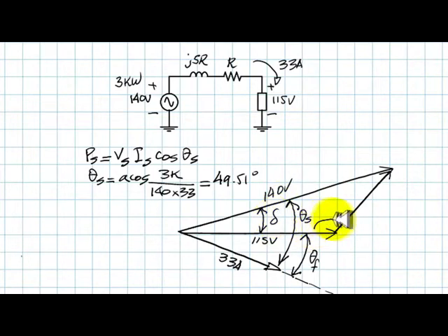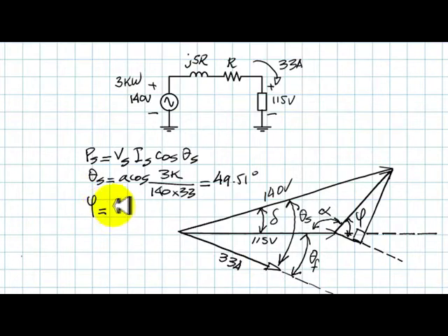Can we find perhaps this angle? What angle is that? That is alpha, right. How? Well, there is a little triangle here, the cable triangle. Let's draw it. Like so. We can find what angle is this one. Absolutely. That is phi. That is the cable angle. What angle is that? Oh, that is the arctangent of who? X over R. But we don't know R. Do we care? X over R is 5. That's right. We know that angle.